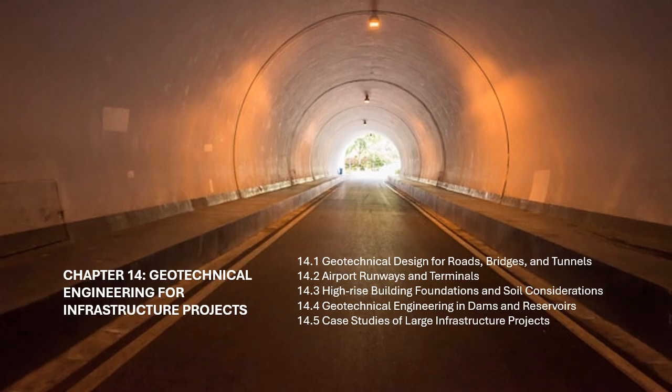14.1.1 Geotechnical Considerations for Roads. Road design is influenced by various geotechnical factors, such as soil properties, subgrade strength, drainage conditions, and environmental factors. A thorough geotechnical investigation is required to determine the suitability of the foundation, materials, and design appropriate pavement structures.